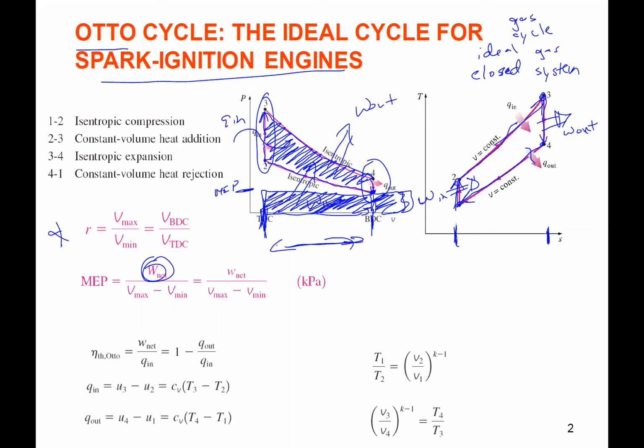Okay. All right, from the calculation, we have a heat engine, right? Okay, where work net is the desired output, required input is Q in, we have that for our thermal efficiency. Or if we do conservation of energy around the whole cycle, right, you have Q in, Q out, work in, or work net is work out minus work in, right? So then you can relate Q in minus Q out equal to work net, right? And that's what's kind of done here, right? This is also this 1 over is Q out over Q in, right?